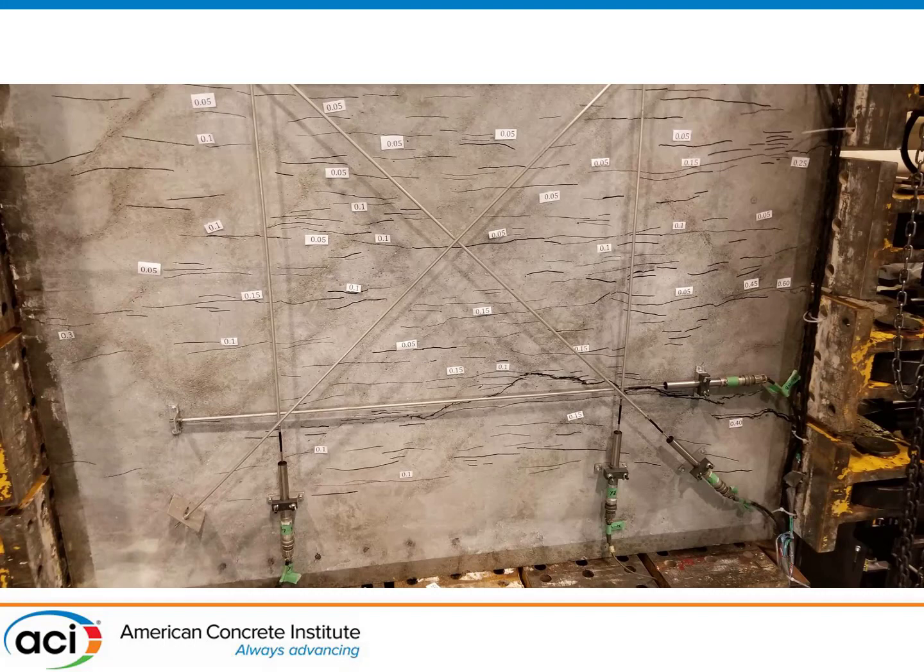As the load got higher, eventually those cracks got wider. If you have sharp eyes, you can see some of the cracks are now at 0.15 millimeters wide. And more importantly, there's one big crack near the bottom that has actually become a problem. We can see down here near the bottom. Because of the way the machine works, we can only have cracks at the outer faces between the steel plates. And so there's some concentration of crack width there, and that started an unzipping process.